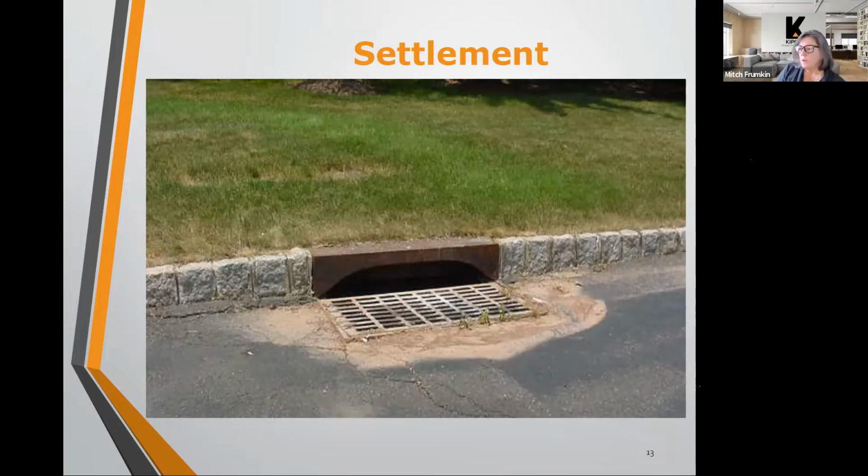So this is a very common issue in communities that are doing their first pavement remediation, because all that soil consolidation has happened over time, and now is their chance to repair it as part of a pavement project. So in an area like this, we would call out a full depth repair around this catch basin, where they remove all the pavement layers. They may need to recompact around the box and put in a new full depth pavement.